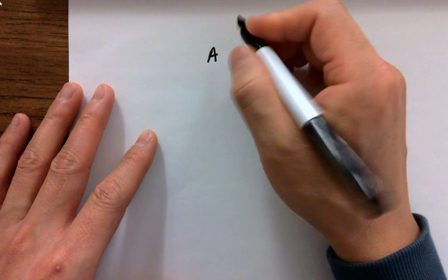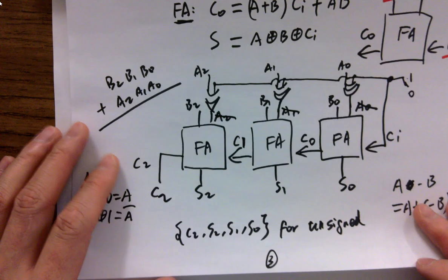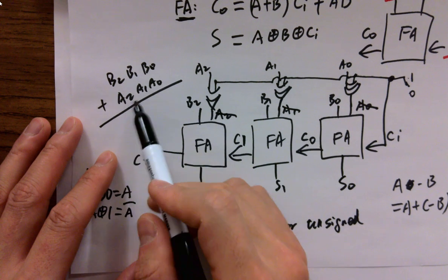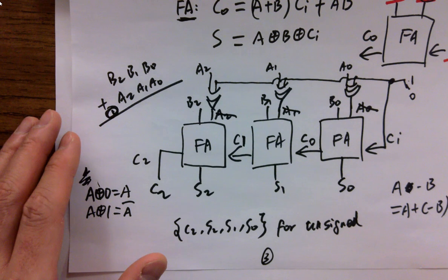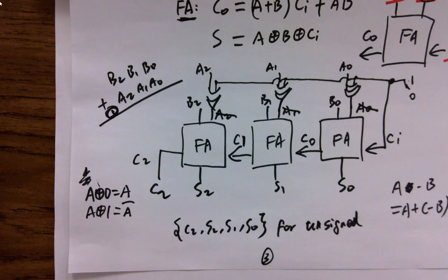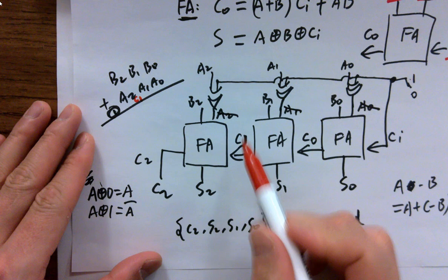So now let's derive the logic here. How do we deal with the final results? When there's an overflow, what kind of bits need to be manipulated? So let's start with A. Okay, let's look at the structure really quick. What are the bits that really matter to determine the C2, the carry out here? What are the numbers that matter? They can be physical bits, or some intermediate values generated by the previous bits. A2 and B2, and also the little carry here, right? Yeah, which is C1.